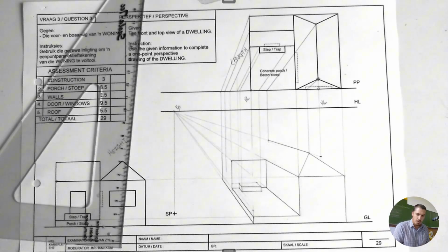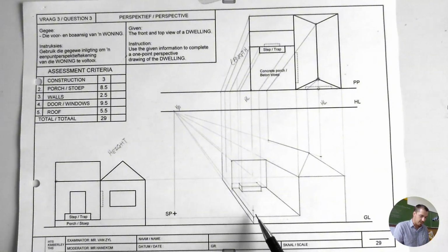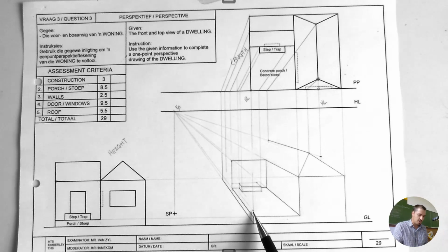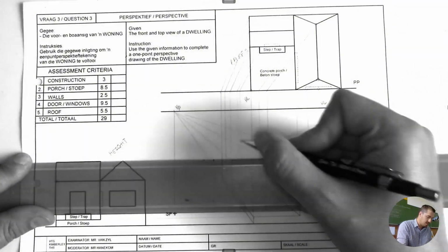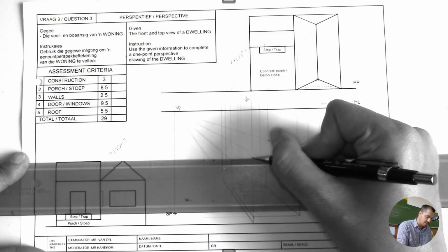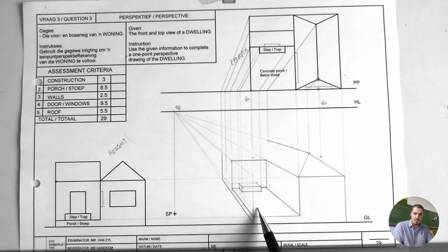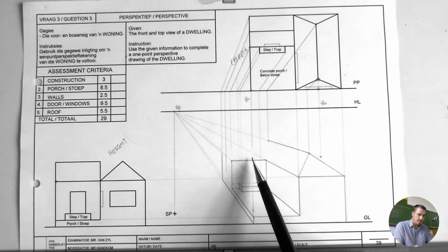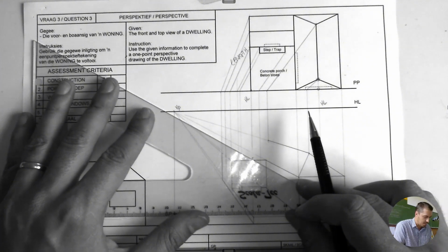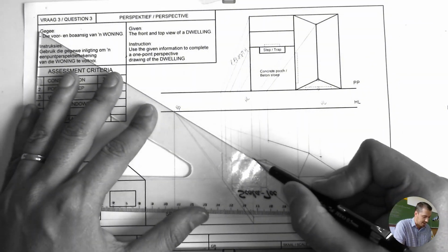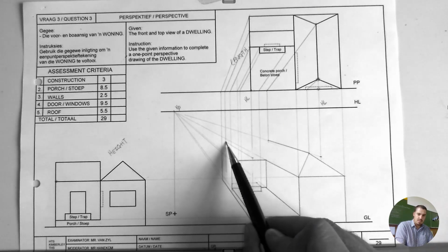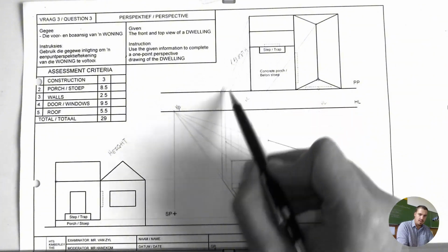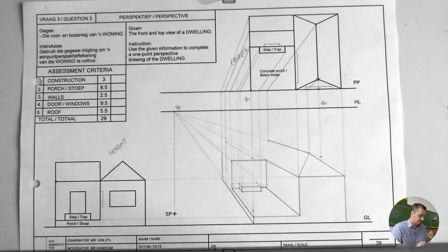How do I get the height for the roof? We need to have a reference point. This line that we initially started with. This line here, where we took the height for the step as well. You are going to take the roof height and you're going to put it on that same line. Alright, so there's the line going up to there. That point goes to the vanishing point, where that intersects on that roof line I just made. So this goes back, and where that intersects with this point, which is the roof point there, that is where my roof connects to.